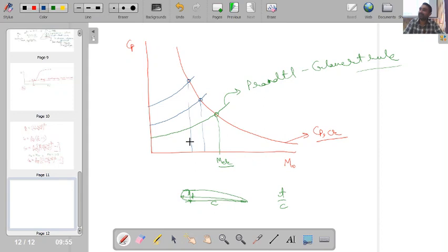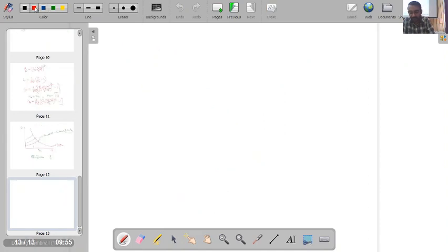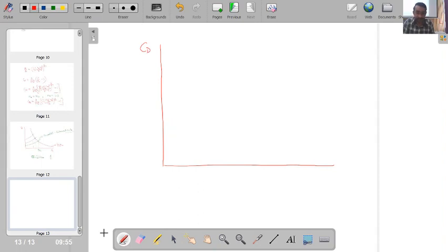Is this point clear? Upon increasing the thickness of the aerofoil, the critical Mach number, corresponding to which the Mach number becomes 1 at the point of maximum acceleration, is actually going down. This can also be seen with the help of this curve. People have performed experiments and found the drag coefficient, and this drag coefficient is represented as a function of M infinity.